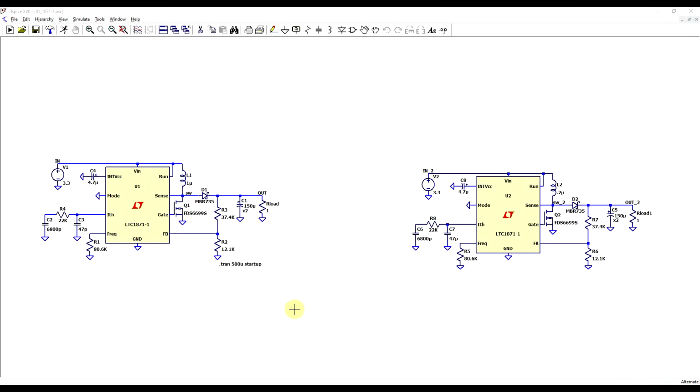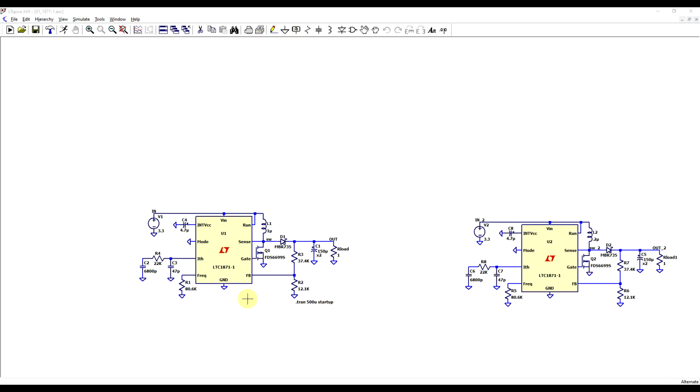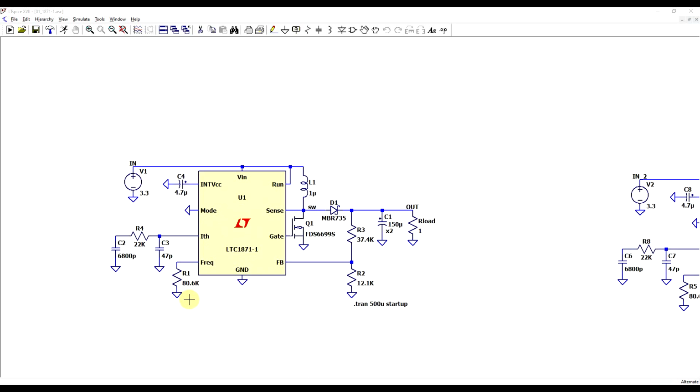In general, having a larger current variation and higher current peaks, as is characteristic for discontinuous conduction mode, will cause greater electromagnetic interference problems. The larger the AC component of the waveforms, the more noise they will generate. But other than the current, it's important to also observe the voltage in such a converter, since this usually has a very specific shape. To highlight this, I will be performing some LTspice simulations on a modified version of one of the default schematics present in the library.